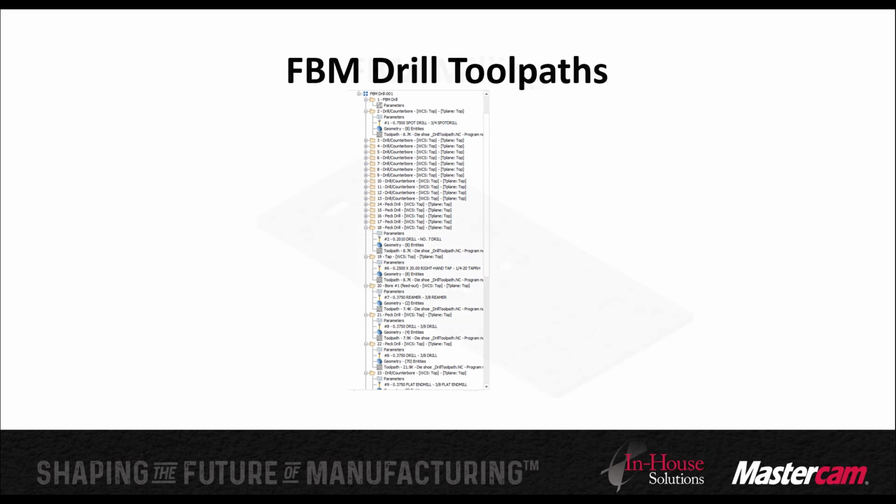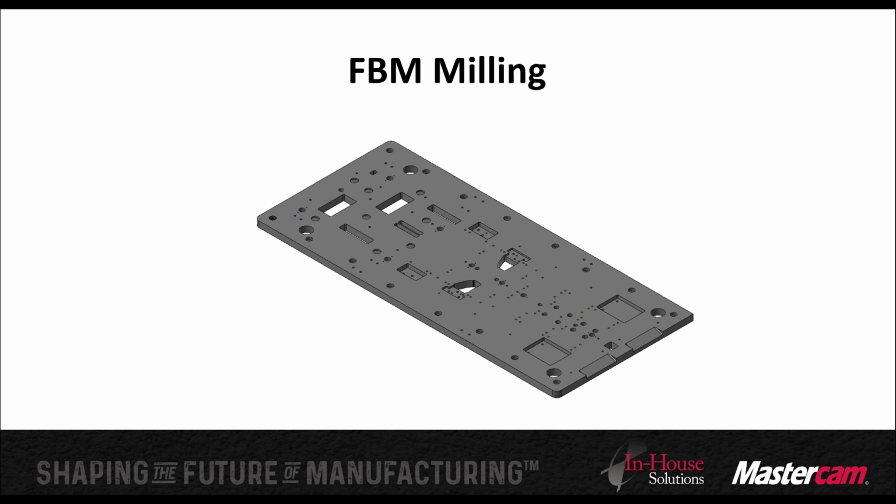To demonstrate Mastercam FBM Mill and FBM Drill strategies, I'm going to machine a die shoe part. I will be starting with the FBM milling and set the parameters to face the part, machine all the pockets, and circle mill the larger holes. Time to move to Mastercam.